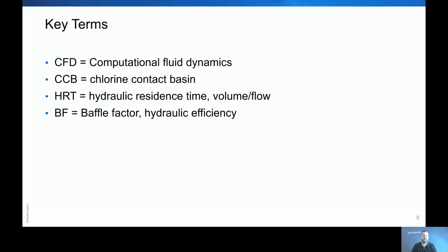The key terms we're going to be using quite a bit today: computational fluid dynamics, or CFD, a CCB, it's a chlorine contact basin, hydraulic residence time, which is the volume of the basin divided by its flow rate, and the baffle factor, which is the hydraulic efficiency of the basin.